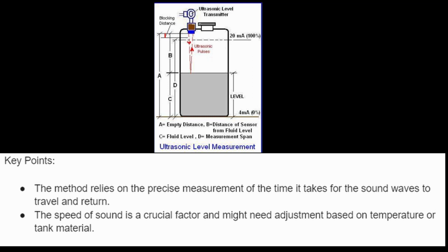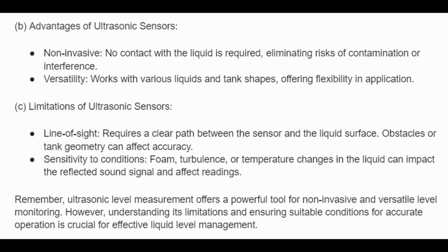Key points. The method relies on the precise measurement of the time it takes for the sound waves to travel and return. The speed of sound is a crucial factor and might need adjustment based on temperature or tank material.